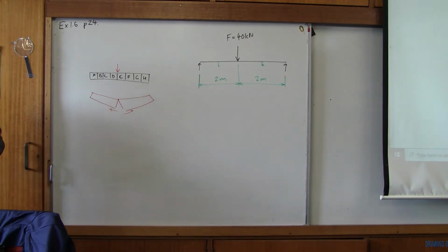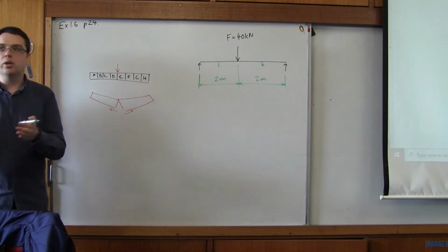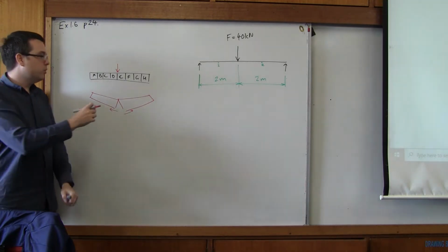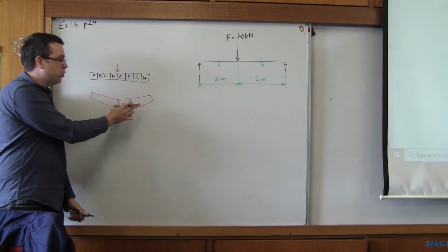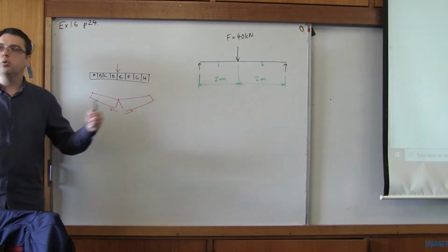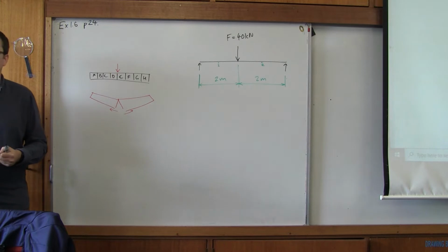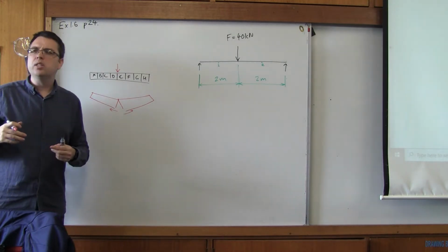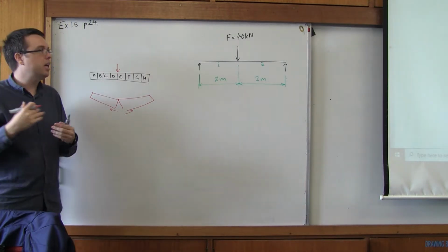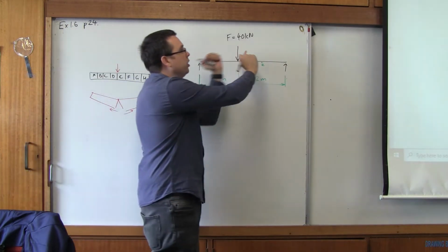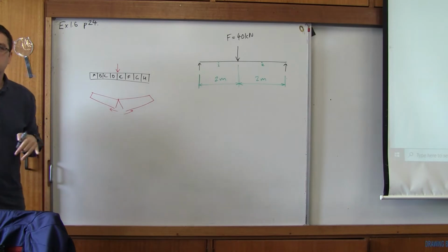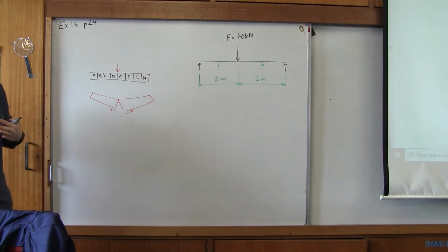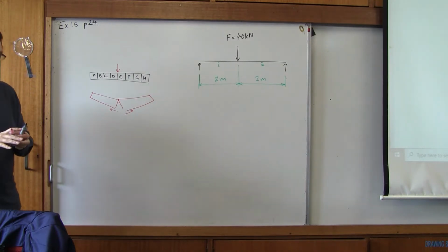If we glued these blocks together, and I snapped them, and I looked at the video and I saw that how it failed is that the bottom was being pulled away. What do we call pulling forces? Tension, right? So it's failing in tension. But we said that that's different, right? The tension is an axial force. Tension is when we're pulling along the beam, yet we can see that we're producing tension in this case as well. But that's more a bending consideration. I'm going to come back to that. It's going to make sense in a second.